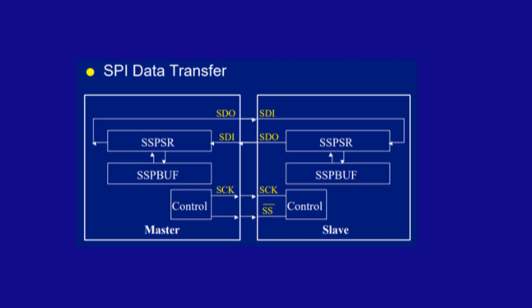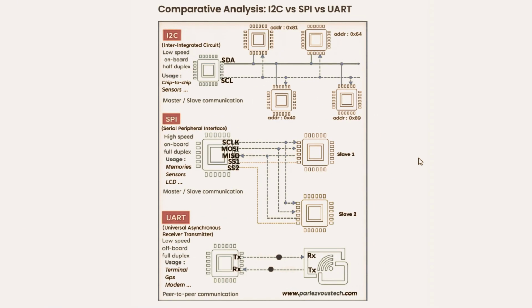The flow is just: CS goes low. Clock starts pulsing. On the active clock edge, master puts a bit on MOSI, slave reads it. Simultaneously, slave puts a bit on MISO, master reads it. This repeats bit by bit, byte by byte, until the master stops clocking and raises the CS line high. The slave just follows the master's rhythm. Okay, that makes sense. The CS line going low and high defines the overall transaction boundary, and the clock keeps everything aligned bit by bit within that boundary.